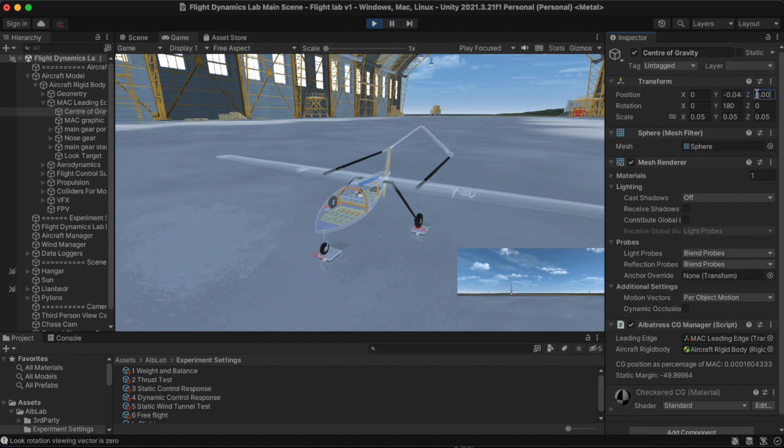As we know, the distance and the forces are shown on a scale. Therefore, we can calculate the moment arm of them in order to find center of gravity. So now, by changing the z value, we can see the numbers on scale are different, since the location of CG is changed.